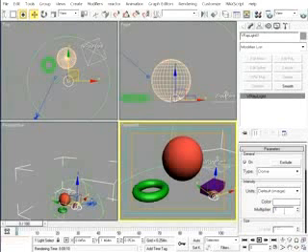For interiors, a larger value like 30, however, might be needed to get enough illumination to light the inside of a building. Likewise, the less illumination your skylight provides, the more apt the light is to produce splotches in the shadows. And this we'll look at in more detail in the next module on lights, how to improve the shadow quality of any type of light.